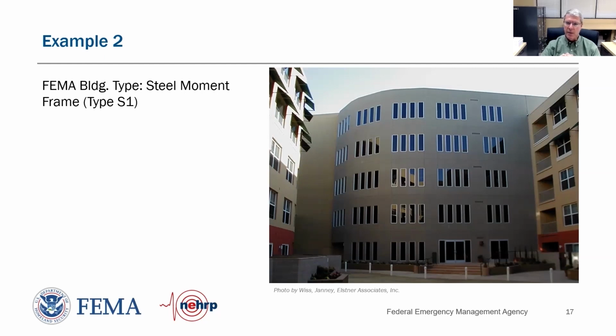But what about the building on the right? It is a different architectural exterior than the building in the back. We're not reviewing these, but nevertheless, it's instructive to take a look at them. How is that building on the right framing into the building in the back in terms of our floor elevations? They look to be not aligned. Yeah, not aligned. So that's one of our adjacency criteria we walk through, right?